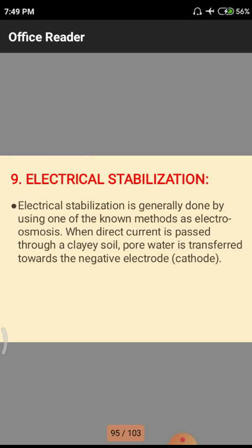Normally in the previous cases of dewatering techniques, we utilize different engineering principles to remove the water in coarse grain and fine grain particles. Why? Because in coarse grain particles we have some voids between the particles, since their granular size is very large compared to fine grain soils or clay soils, so that there may be some gaps. In those gaps there may be stacking of water, so we use different engineering principles like slopes and cambers that are maintained.